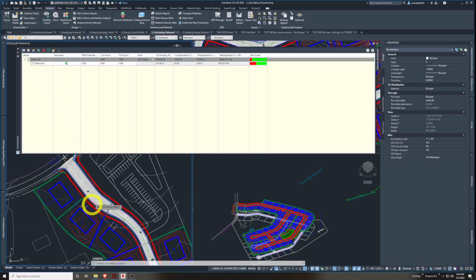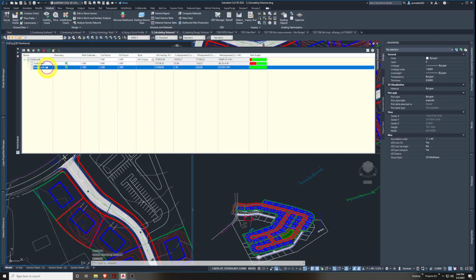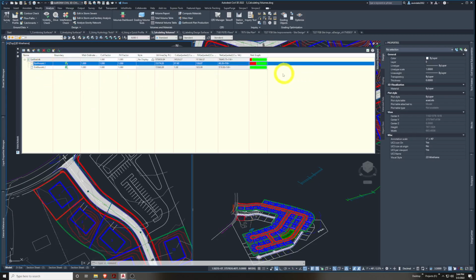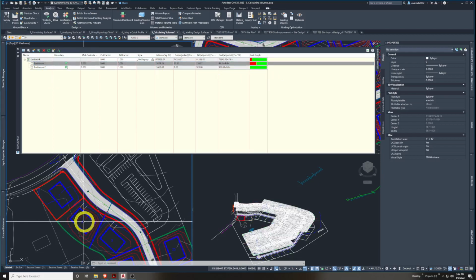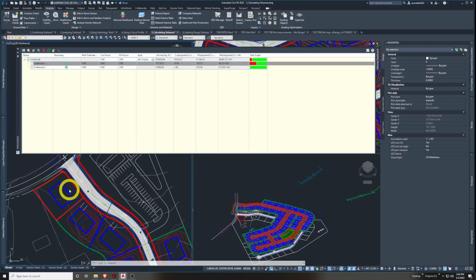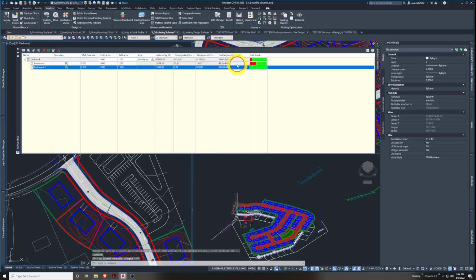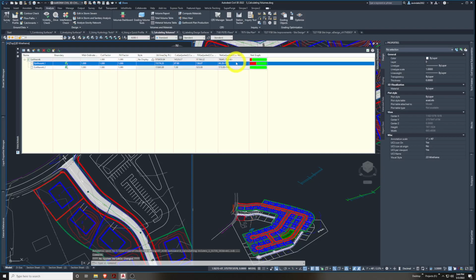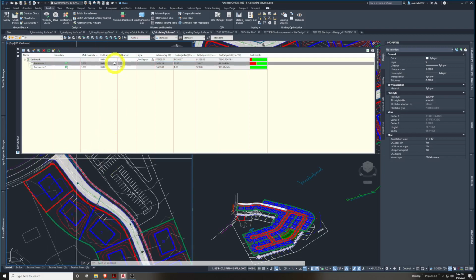I'll do another one of lot 2, pick this parcel. It does one earthwork 2. I can rename these. But this shows lot 2 is almost all solid fill. It's green. Lot 1 is very balanced. It shows not much fill, 50 cubic yards, which is 5 dump trucks worth of import needed. It's somewhat more balanced. And so we can get really surgical that way, which is cool to see all the different areas of volume and very specific small zones of our design.